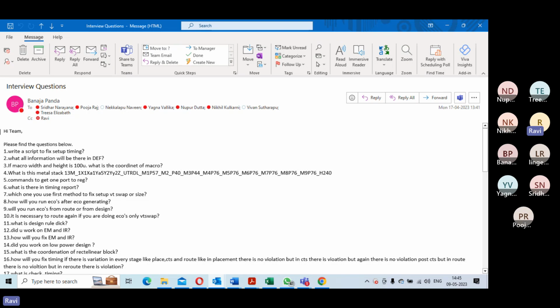If anything is between 50 picosecond and 80 picosecond, then you try to just upsize it to just 2x. So you have to take some heuristics like that. You have to take some decisions that your script should do, that it should only do 2x here, and here I can do 4x.